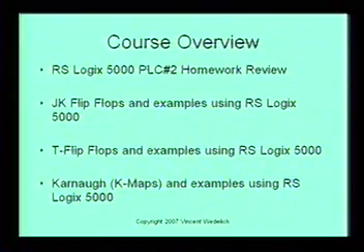And again, the JK flip-flop, T flip-flop, Karnaugh maps, that's all really for the fundamentals of engineering exam. But it's really good that you understand how to program these, because you can take real-world examples, logical examples, and easily convert them over into ladder logic programs. Well, you can take AND gates, OR gates, exclusive OR gates, even flip-flops, the ideas behind flip-flops, and convert them over into logic. That's when you start to be able to take processes and convert those into code as well. It's really important that you understand that.